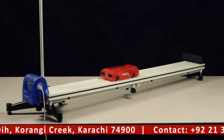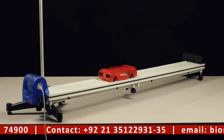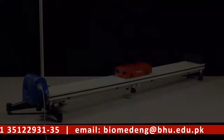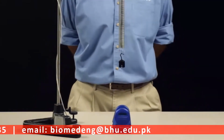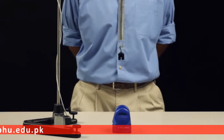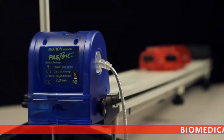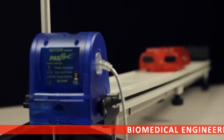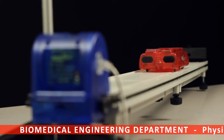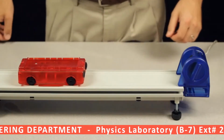Given the time it takes the pulses to make a round trip, and the speed of sound in air, the sensor can indirectly measure the distance or position between itself and the target object. The sensor then uses subsequent position measurements to determine the target object's velocity, and subsequent velocity measurements to determine its acceleration. Because the sensor uses ultrasound, it's sensitive to obstructions that may block or be near the target object when making measurements. Be sure to clear any of these obstructions from the one-dimensional path of the sensor when making measurements.